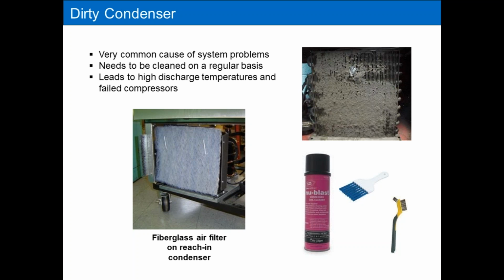Now I've also got on the screen a sample picture of a filter, a fiberglass filter or even a mesh filter that guys put on condensers. And honestly, I'm kind of in between on whether this is a good approach or not. I don't have any empirical data on whether or not this adversely affects the airflow through the condenser. So bearing that aside, let's assume that it doesn't affect the airflow through the condenser. If you push that to the side, that is actually a very good technique to use to keep these condensers clean.